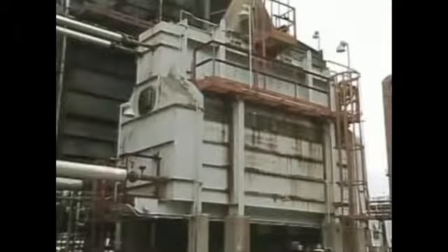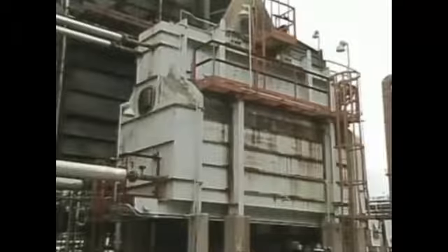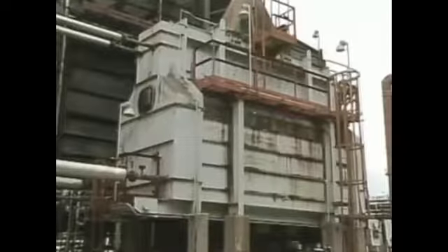Now, fired reboilers can experience some of the same problems as shell and tube reboilers, including tube fouling and tube leaks. But since fired reboilers burn fuel to heat the bottom's liquid, they sometimes experience combustion problems as well. For example, too little airflow can cause incomplete combustion in the furnace. As a result, more than the necessary amount of fuel is burned to maintain the temperature in the bottom of the column at set point.